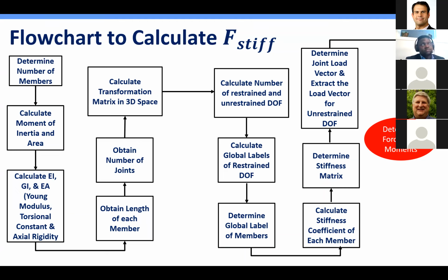Wow. Normally one doesn't care much if it's a big hole like 12 1/4 with 5 1/2 inch drill pipe, but if you've got 5 1/2 or 5 7/8 inch drill pipe in an 8 1/2 inch hole, and you've got 20,000 feet of that, those are big numbers. Those are really big numbers. Wow, it sounds like a big delta. Yeah, it is. I'm looking at some data pulled up on another screen this morning on a land US well that shows this effect. Wow, great.